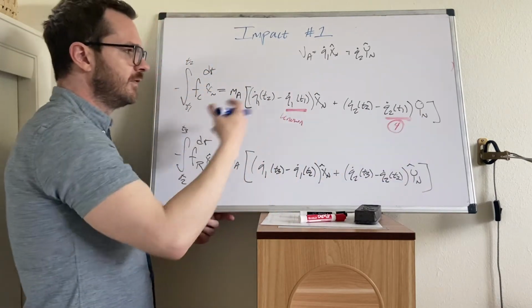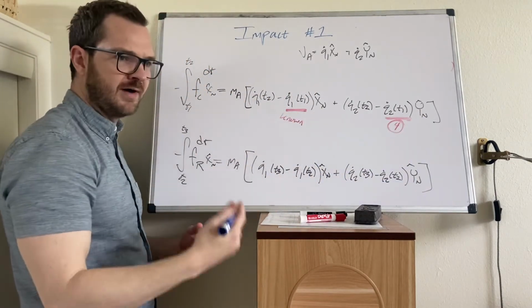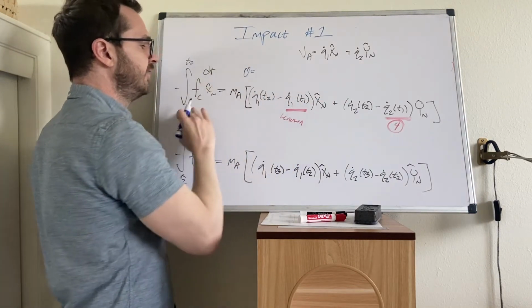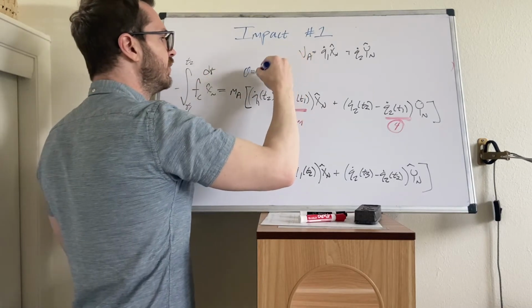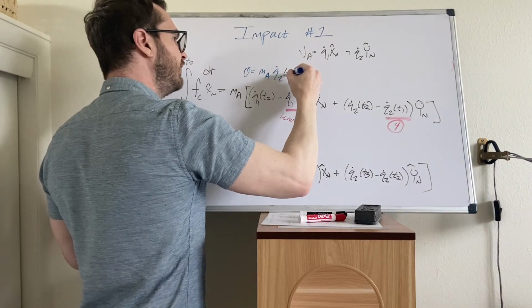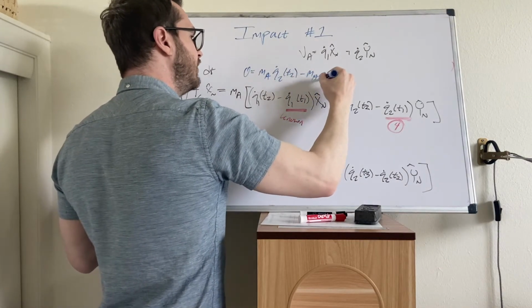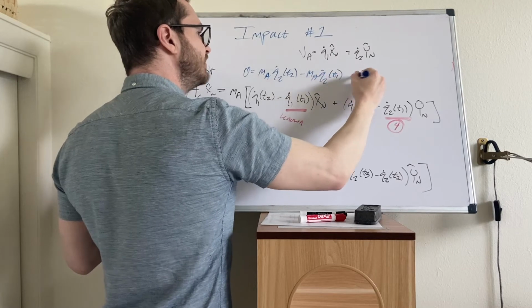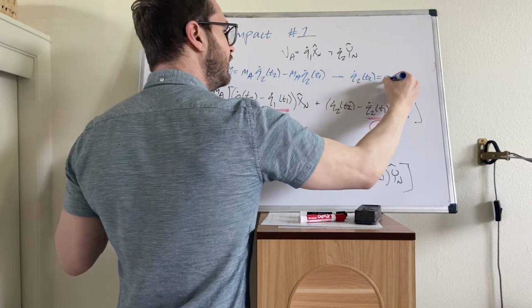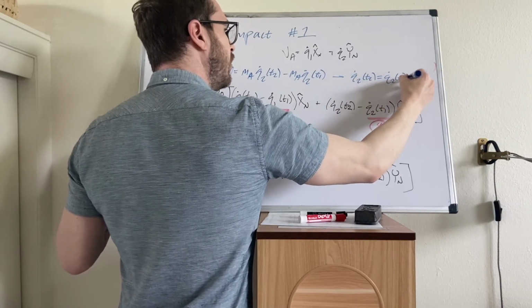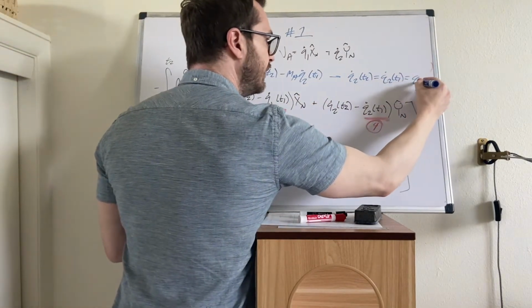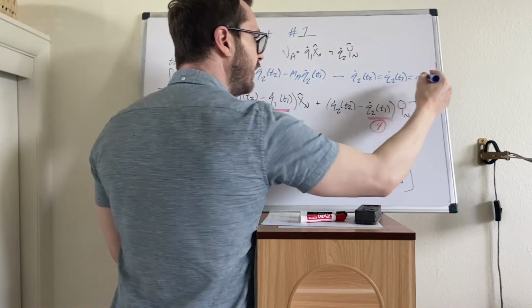Well, if we took these equations and did a dot product with the y hat n direction, then the left-hand side is 0, and 0 is going to equal ma q2 dot time 2 minus ma q2 dot time 1, which means that q2 dot at time 2 equals q2 dot at time 1, and we could do the same thing to the third equation, and we're going to get q2 dot at time 3 also.